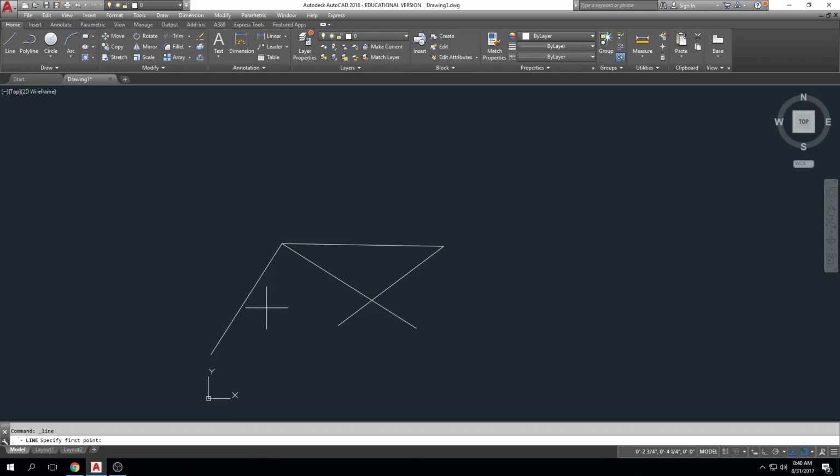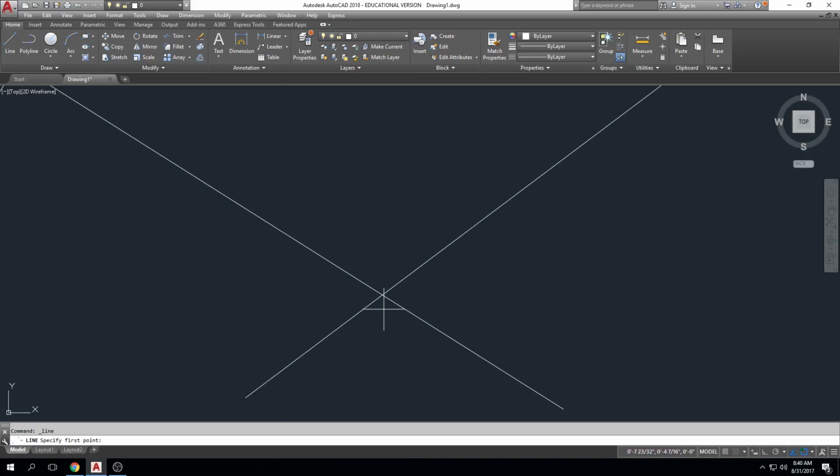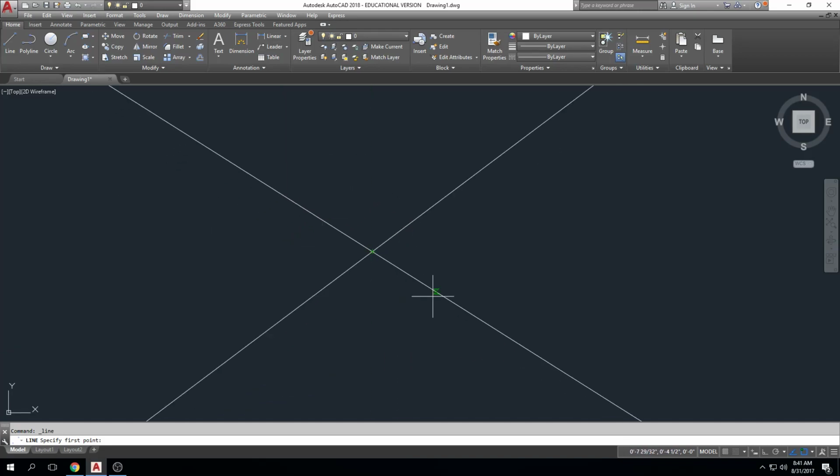And so there is a way where I can force AutoCAD not to sense any object snaps except for one. So generally speaking, every object snap is running, everyone is engaged, right? And it will just kind of automatically sense. There are times when I am close in and I get a lot of object snaps happening, and I think, oh, I just want the endpoint snap, okay?